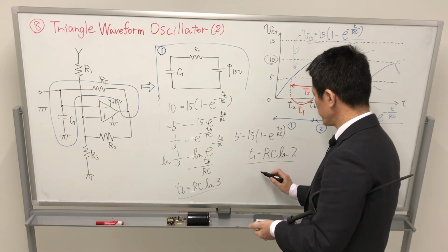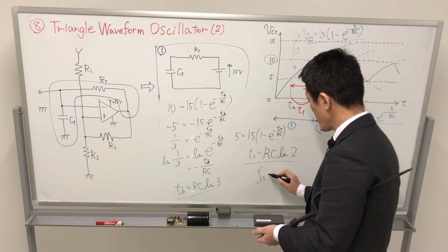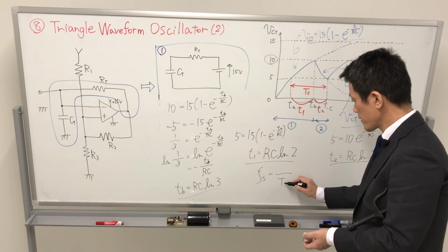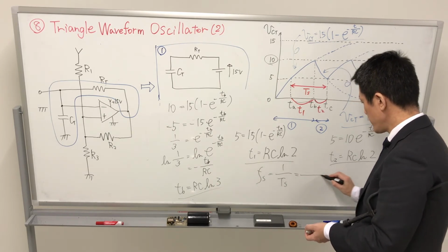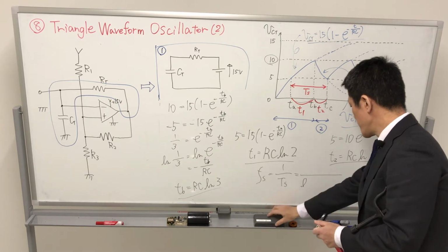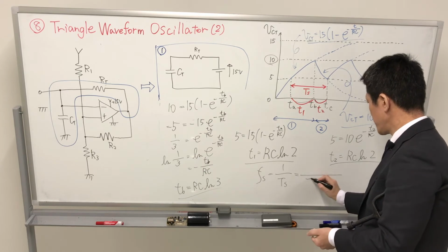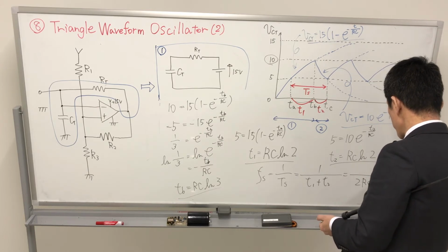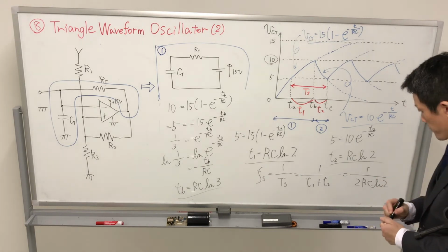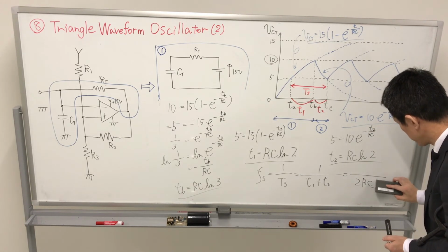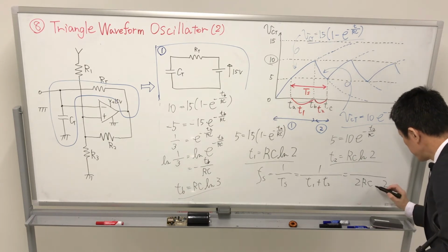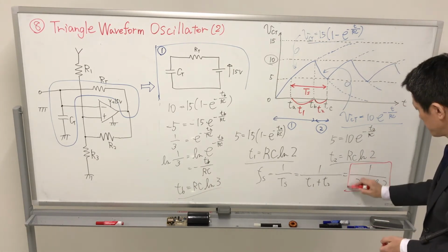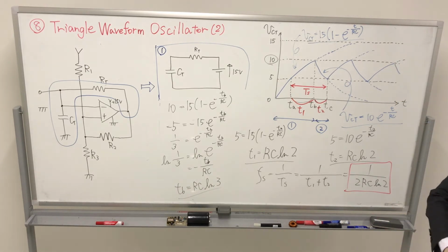So if you directly obtain the switching frequency of the boost chopper, you can obtain TS and invert it, and obtain T1 plus T2. This is the switching frequency.